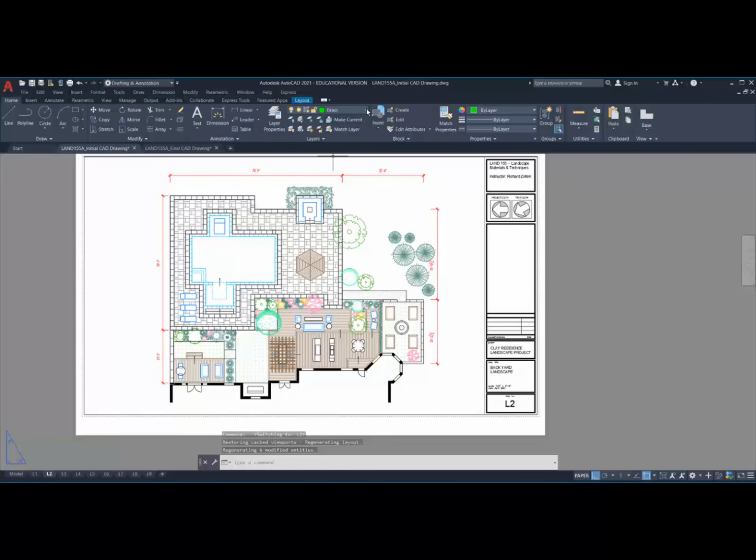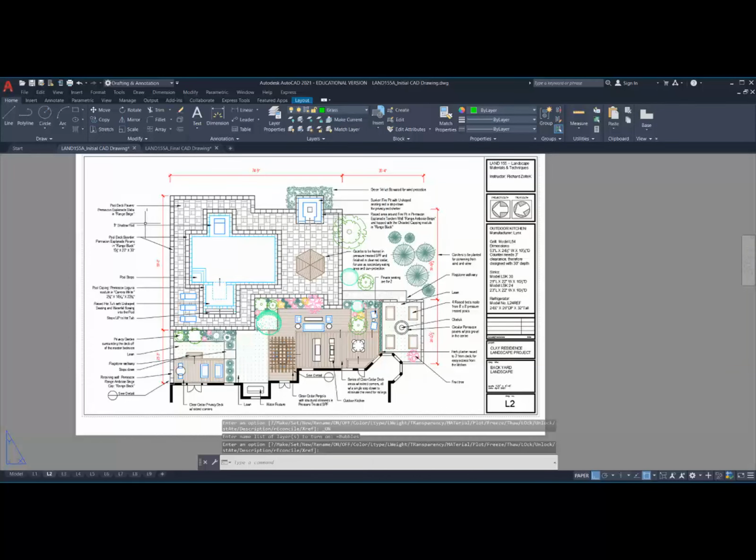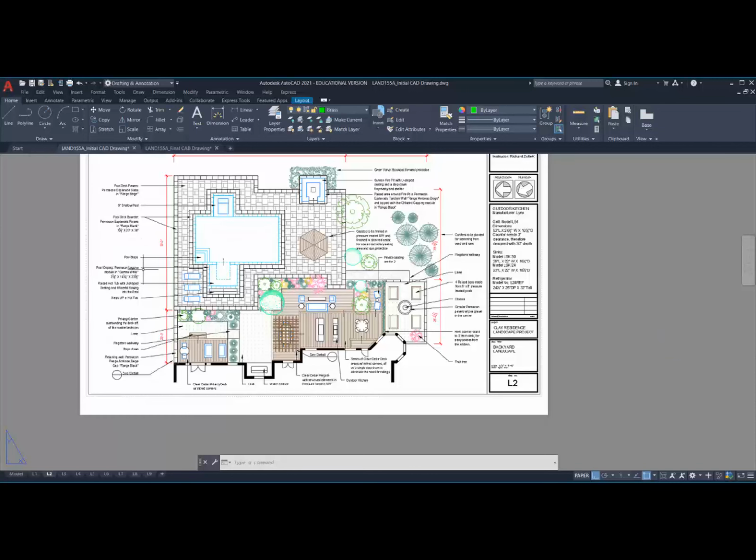And then finally, once this is done, you'll be adding your notes. And the notes are critical because they basically tell the story of what is actually here. So these notes, they're carefully planned out, they're carefully lined out, identify all the elements. Now, some of them are far more specific than what we need at this time, but if this was part of the project planning process where you already know what materials they are, you start including them in the notes. And see how the notes don't interfere with the dimensions, and they're all clean and off to one side and in a straight row.